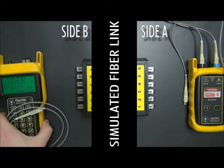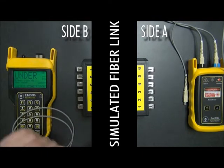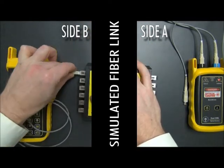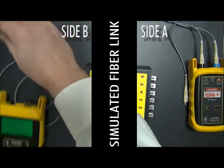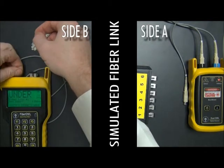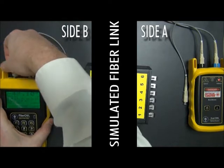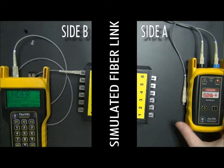The first thing we need to do is make sure that we plug into port 1. Typically, we're going to start at port 1 and then move on until we're done with all the fibers in that particular link. So what we're going to do is we're going to do that now. We're going to plug into port number 1. All right, now we plug the light source in the port 1.